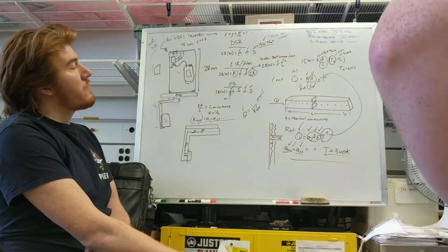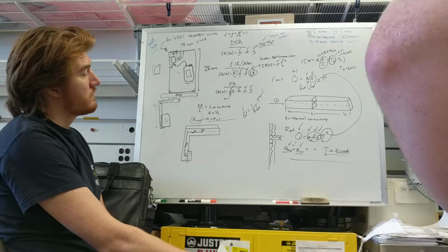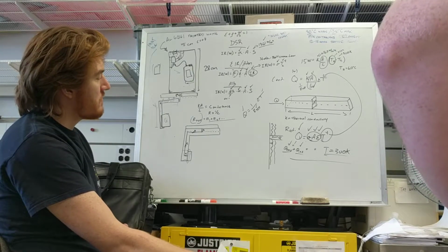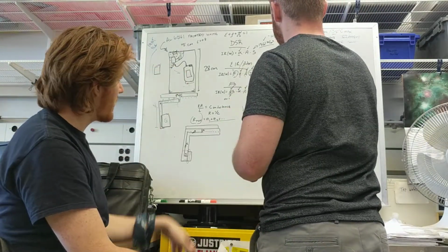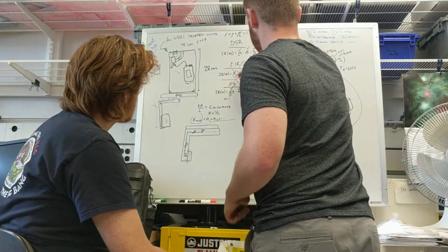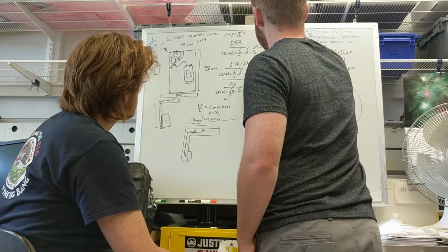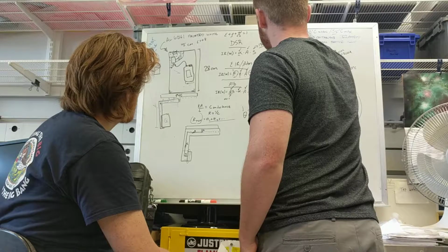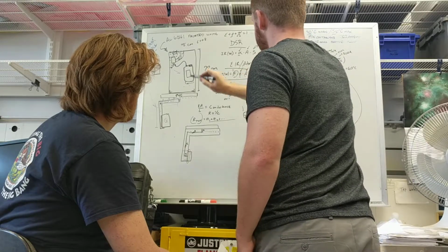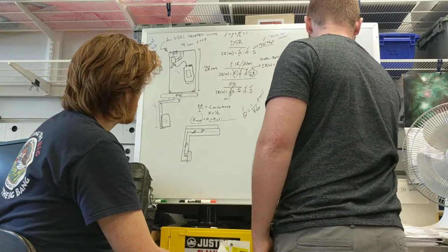I mean, that calculation is not difficult, right? You get the T from your radiation equation, so all you have to do is sit down for 20 minutes and literally run this. I mean, F is 1, this is 0.8, this is 15 by 15 centimeters, right? And this can be computed by multiplying two numbers together. So then you know your Q, and you know all this other stuff.